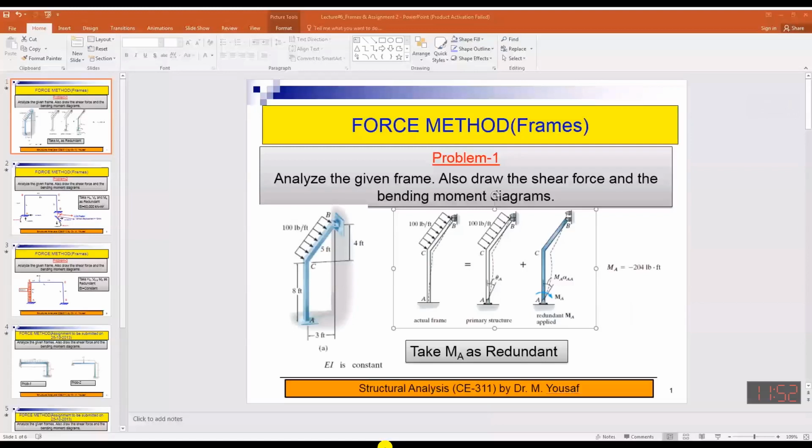Now this force, this is acting along the local axis. Now if I resolve it, then you will see this is given over there. Detail is given 500. If I resolve it into two components, according to the global axis, 300 force will be acting downward, 400 will be acting rightward. So in accordance with this one, considering this 400, solving this, I will be having 29.17, 300 and 370.83. These are the forces which are acting over there on the structure.